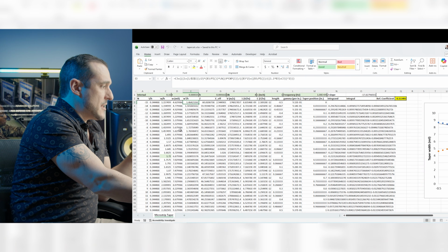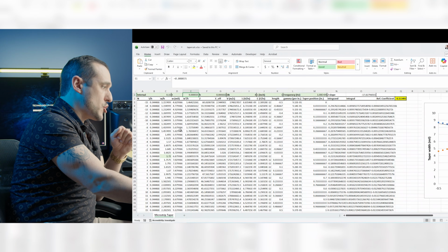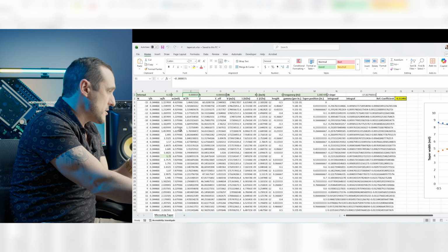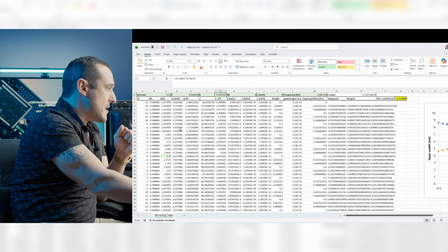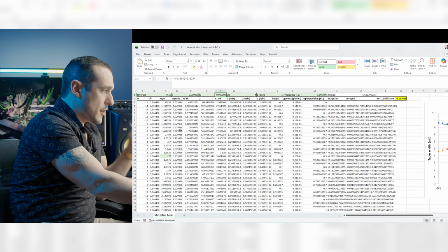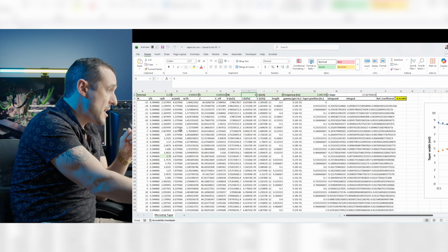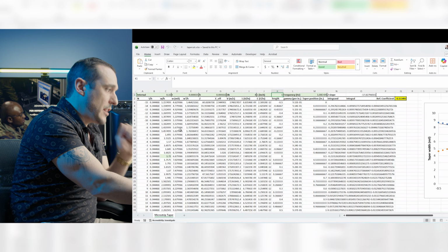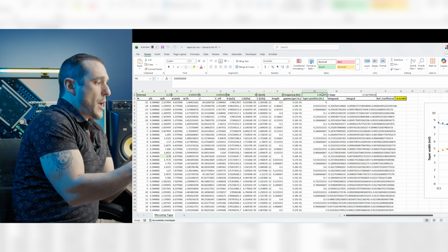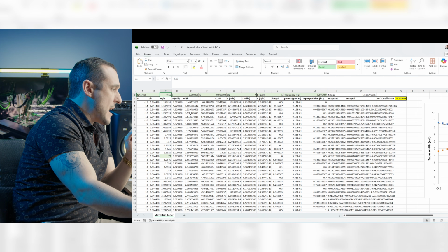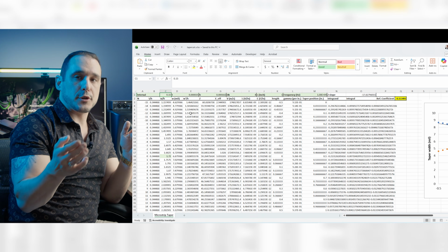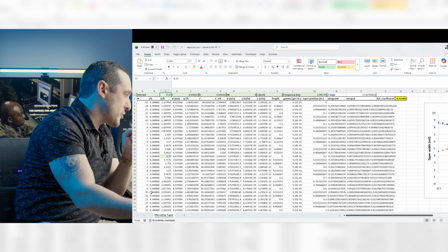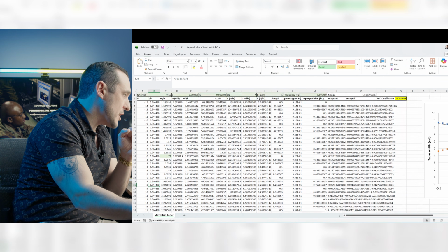So the inputs into this taper calculator are the trace thickness, or the copper weight. Here all of the units are in meters, so we have a trace thickness, and then here we have a substrate thickness. Here it's, for example, 0.1 millimeters. We have a dielectric constant for our substrate, and then we have a target length for our taper. Here we also have an operating frequency, and then here we have this interval term. And this interval term tells us basically how does the width change in each of these 30 steps that we have defined here in column A.